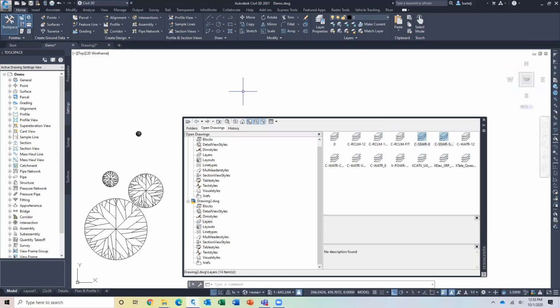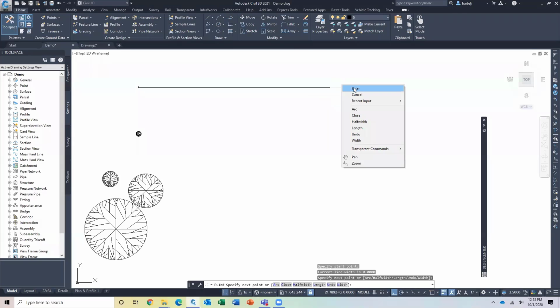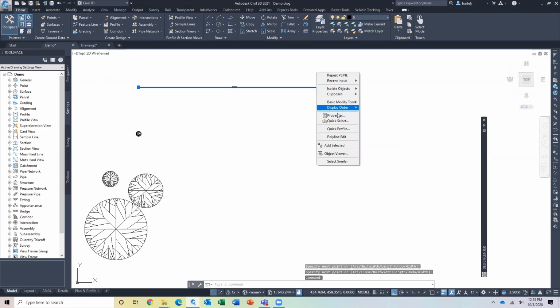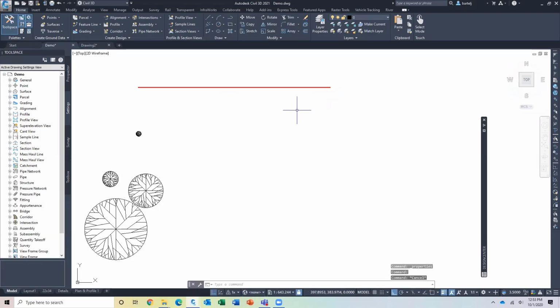Drag it into my file here. If we look in my list now, there are the layers for that. Let's draw just a polyline here to reference a piece of pipe, just to do something quickly. I'm going to grab this and we'll change its properties now to that layer. So we'll say that is the 8-inch sanitary sewer. Okay, now good, but I'd like to do some other things as well with line types. We can have custom line types that actually have objects on the line type that will show us direction of flow. I could do that as well.